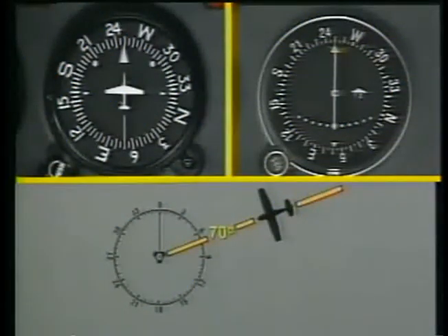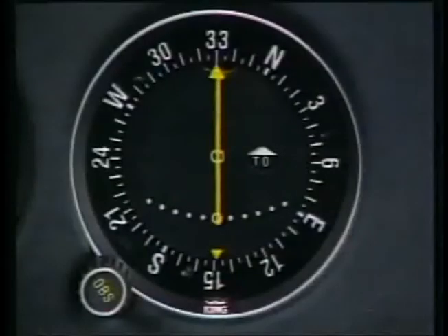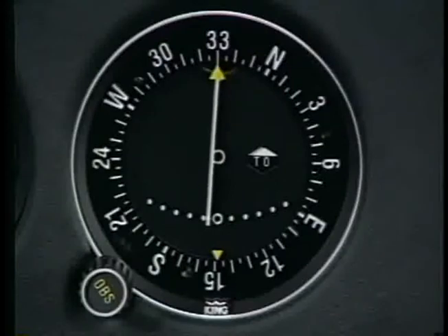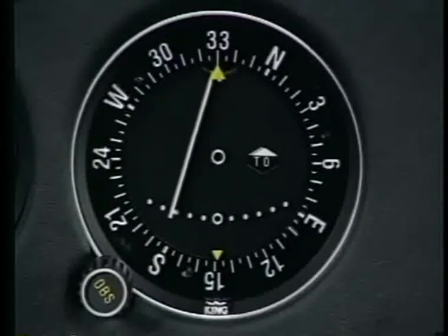It's important to remember that when the VOR and heading indicators are in agreement, a to indication will take you toward the station, while a from indication will take you away from the station. This assumes that there is no wind to drift you off course. The CDI is the component on the VOR indicator that provides wind correction information. If you drift off course, the CDI will point in the direction of your desired course.